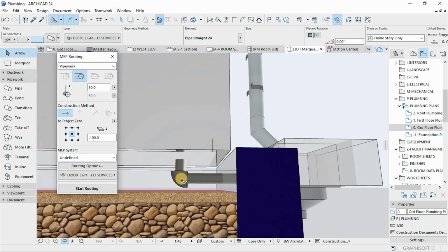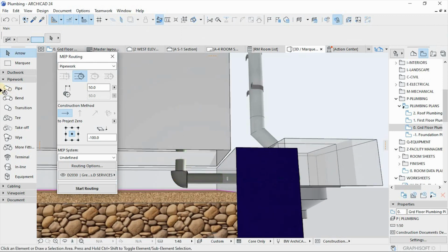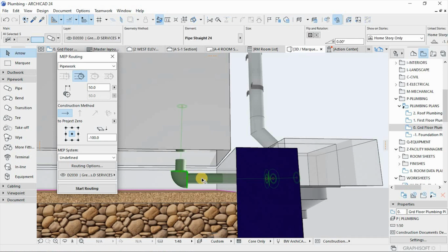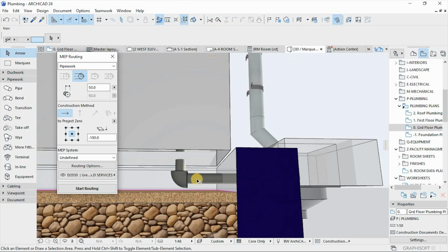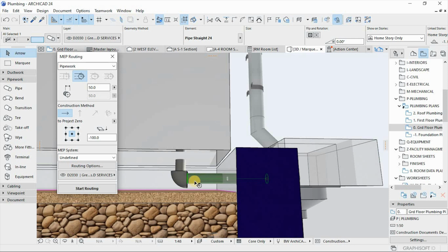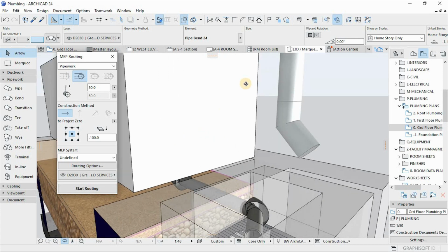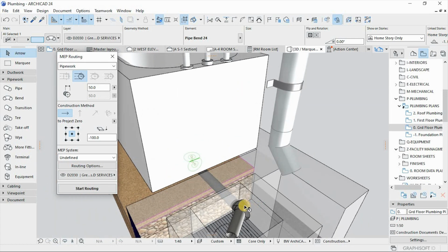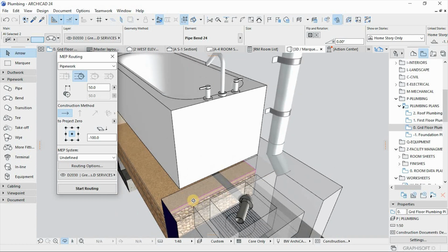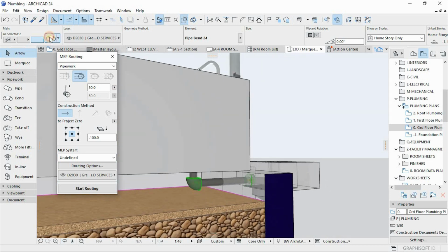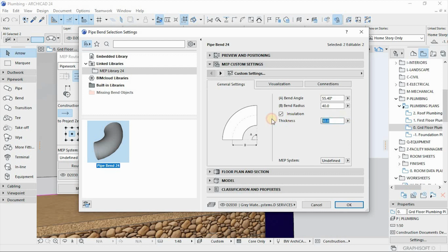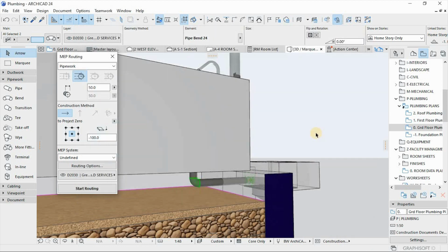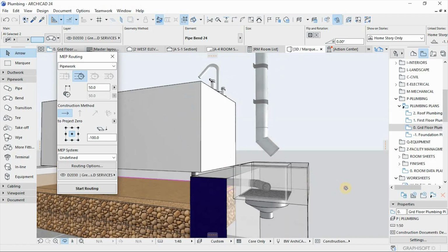And then, because this is a pipe tool, as you can see, we have a pipe tool here and the tool palette, and then we have a bend, a pipe bend tool. So these are a straight pipe tool. Let me suspend the group. These are just normal pipe work, and then these are the bends. So when you change the settings, they are not the same. So you're gonna check, select them, separate, then go back again, and then we do the same. Change the thickness to 5 so that it can give you a nice flow.